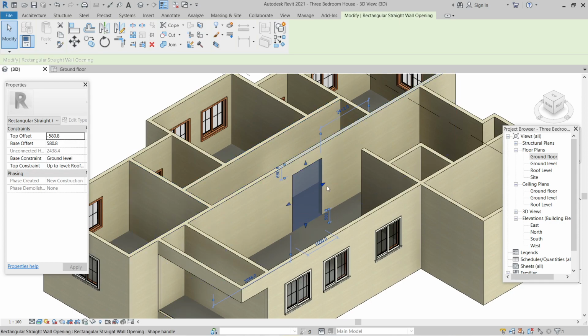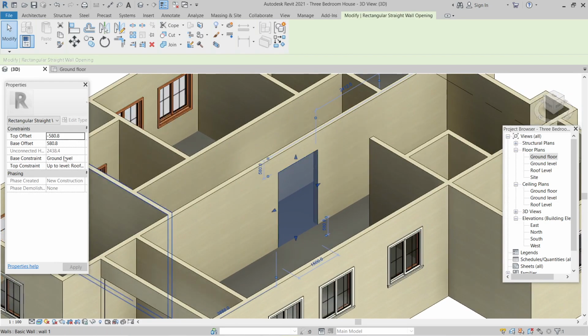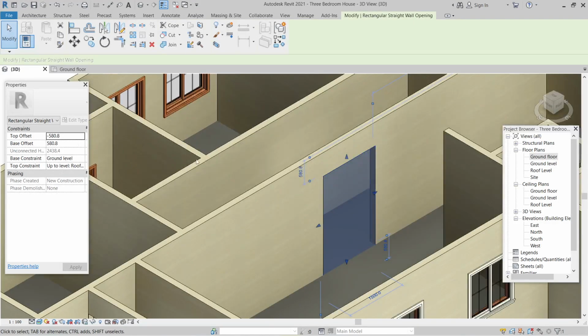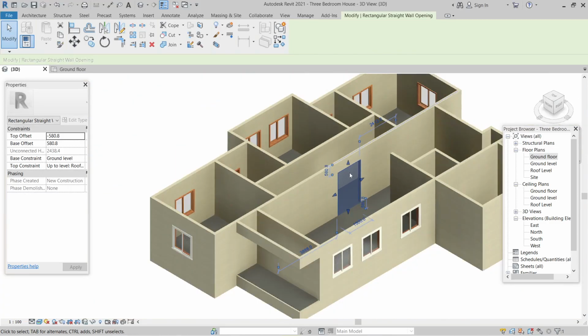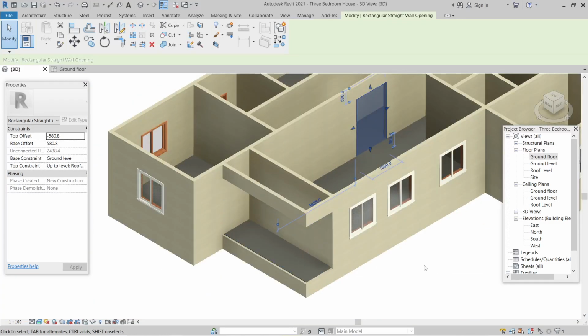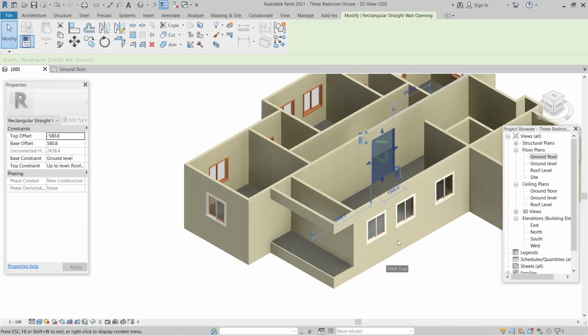That's 7 feet. From the ground floor to the bottom of our lintel is 7 feet. That's a door height. So what we have to do is adjust it so that we know the height left is enough for our lintel to be placed, and then block laying will also continue.